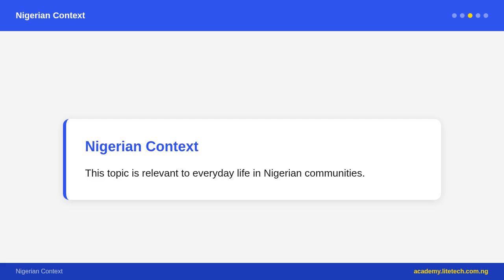A bond in masonry refers to the pattern in which bricks or blocks are laid. Good bonding ensures that the vertical joints between bricks do not line up from one horizontal layer to the next. Overlapping the joints in this way makes the wall much stronger, because loads are spread across many bricks rather than being concentrated along a vertical crack line.